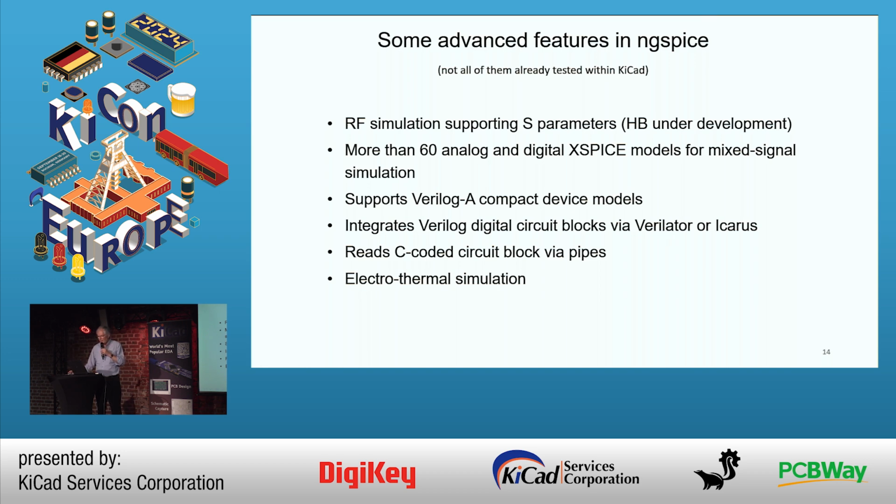Verilog allows you to make digital circuits. We translate them with Verilator or Icarus, and then can attach them to ngspice, and then do a mixed signal simulation. Some analog part, maybe a sensor part or whatever, and some digital part. We can also read C-coded circuit blocks.